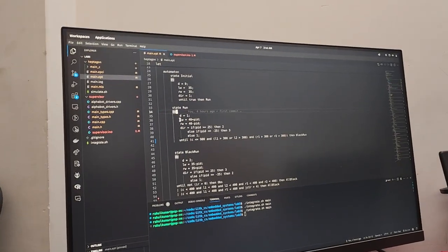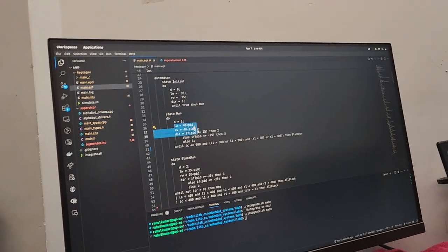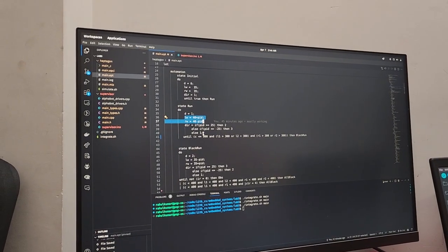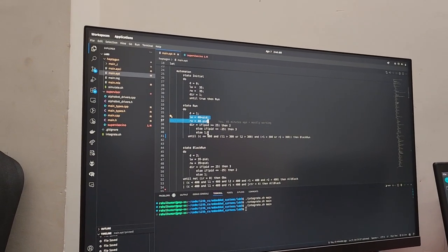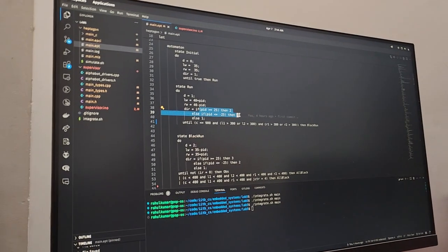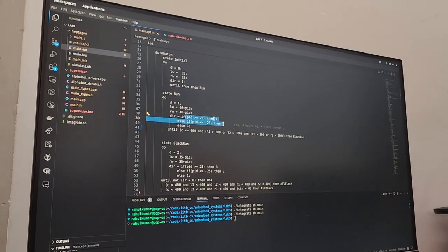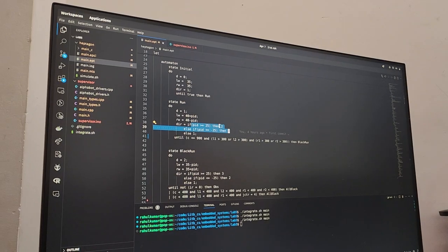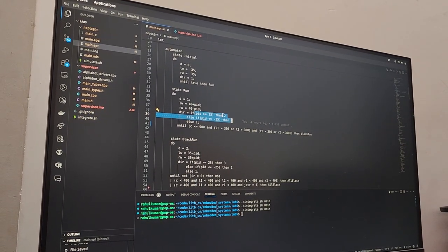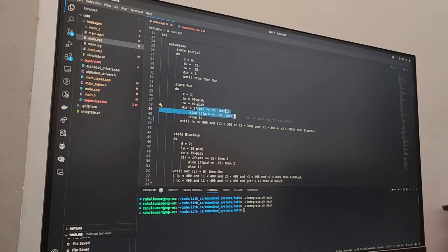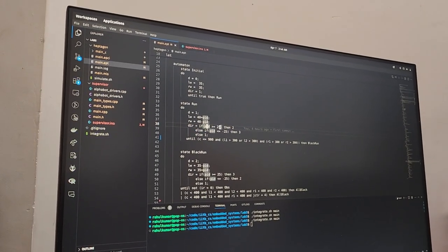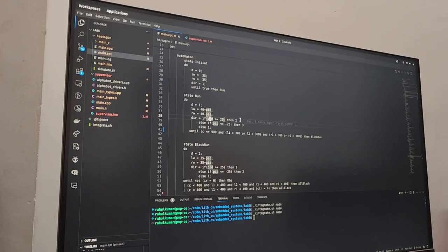What we have used over here is basically just normal PID, and based upon the values of PID we decide what kind of movement the wheels will be doing. For example, if it goes beyond the threshold, that is 25, again this is empirical, instead of moving both the wheels forward, we will do a differential mechanism, that is one wheel will move forward, the other will move backwards, and which one moves forward and which one moves backward depends upon the PID values. So 2 means left turn.